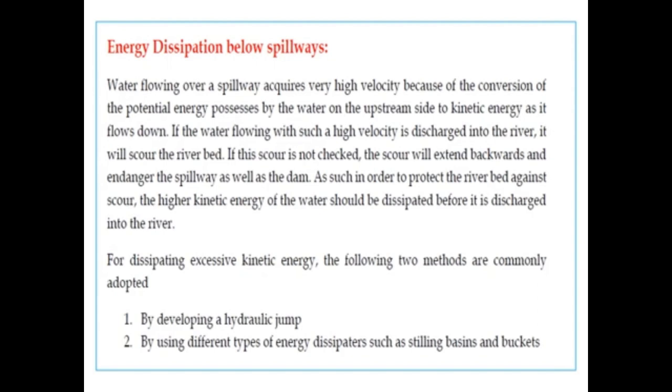So here, for dissipating the kinetic energy, we are following two methods. That is, we have to develop a hydraulic jump at the toe of the spillway, or we can use different types of energy dissipators such as stilling basins and the bucket.